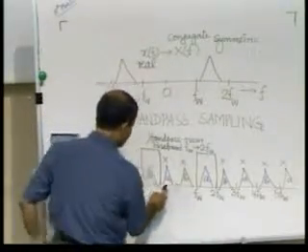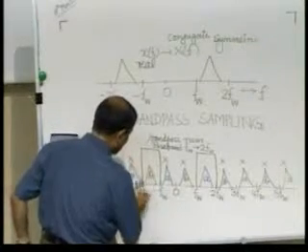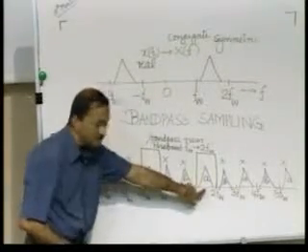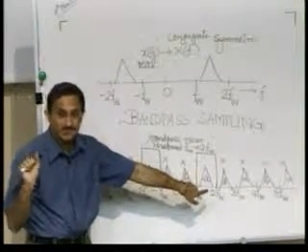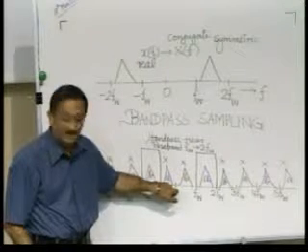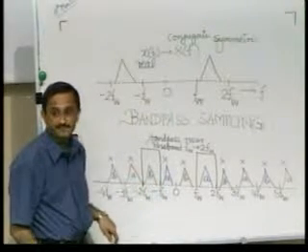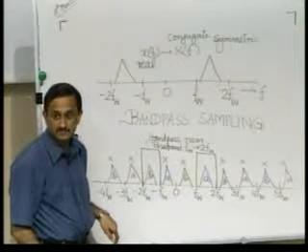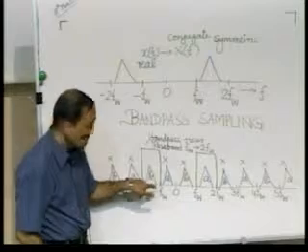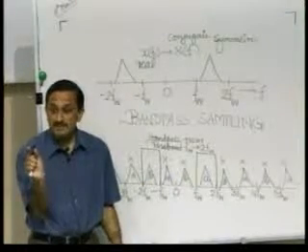So, the A which came here, so of course I am talking about A, isn't it. So, A should have come here, it could have come here. So, you see, what I wanted is it comes here. So, suppose you sample it, in fact even 2FW plus delta is bad. Now, look at this, you have A, it comes here, and you sample exactly at 2FW. But if you sample at a little more than 2FW, this would move backwards and it would come into this. Right. So, this A which was now not falling into the original spectral region interferes with the region minus 2FW plus 2FW to minus FW, even if the sampling rate is just a little more than 2FW.